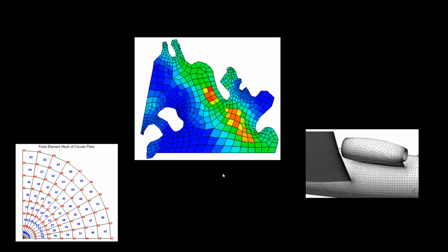That is just a fraction of the time it takes to actually do this meshing, and especially using an algorithm to do it using bilinear elements or these quadrilaterals. That's especially very time consuming, and sometimes it's not possible to do it everywhere. So in some cases you might end up with triangles where you need to connect certain regions where it's not feasible to do it with all of these quadrilaterals.